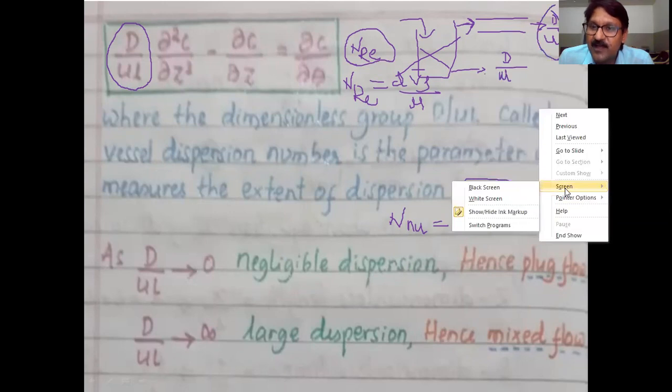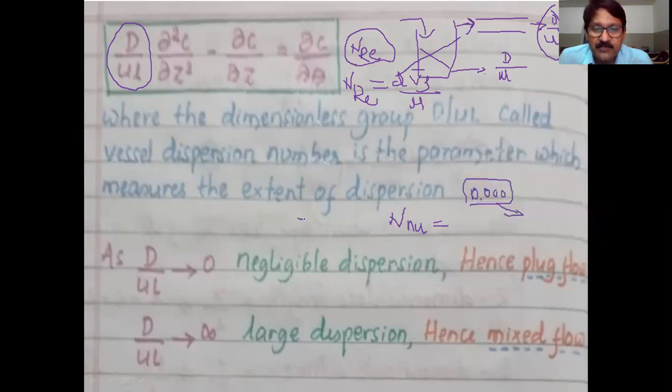Theory is to understand how you are doing, what equations you are using. But when you apply it in the industry, definitely there is a deviation. You cannot get the same value. So therefore you should be able to predict why it is going wrong, what other things should be calculated. Even in thermometer measurement, if you take a thermometer and measure 100, but look at the cover or instruction manual, they will say it is plus or minus 0.05.